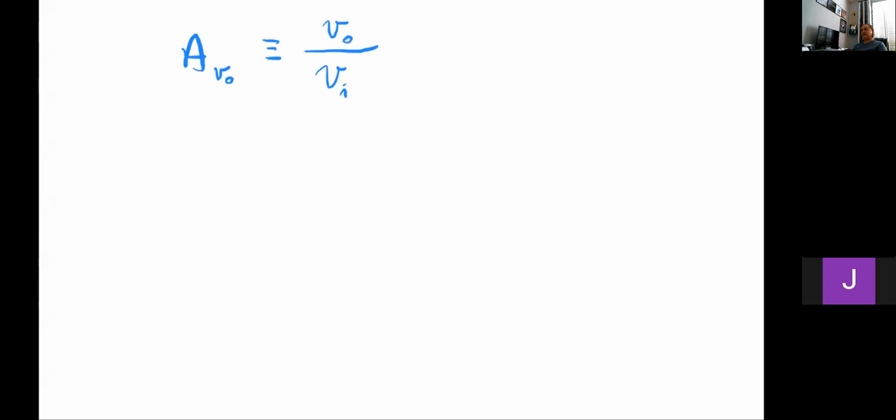The Cascode is a sort of a detour that we're taking. So it's as if we were talking again about just the common source. So don't confuse what we just looked at, which is the one transistor common source with the common gate, with this Cascode implementation. This is just a totally different circuit.